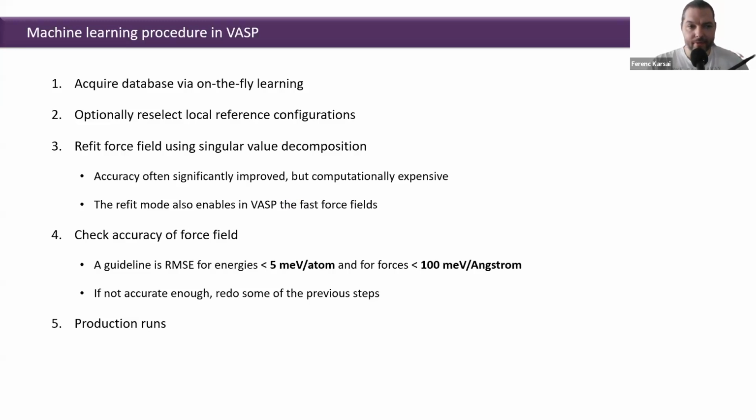And as last, fifth, if you're satisfied, you can start your actual production calculations using only the force field. Don't do production calculations within the on-the-fly mode. This is what I can say.